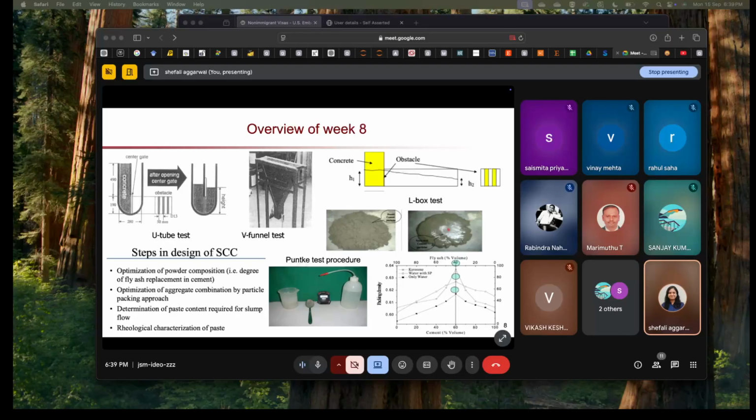of our paste system. In this case, we are using cement paste, a stopwatch, a spoon, and some water, and we will use the powder. Even if we are using any mineral admixture, we will use our base powder. We will keep on adding water in different amounts. This will give us this type of graph.